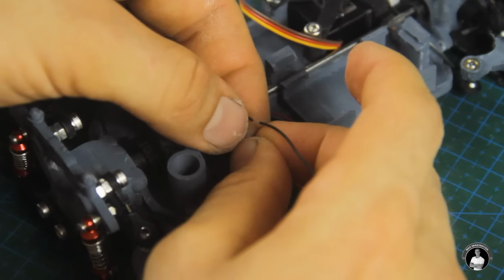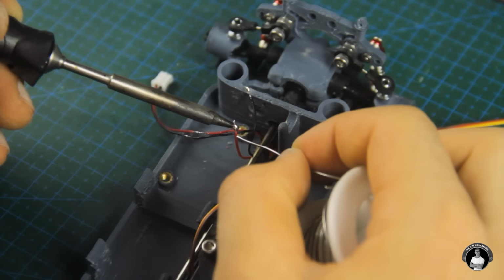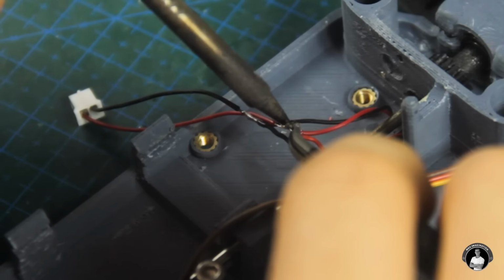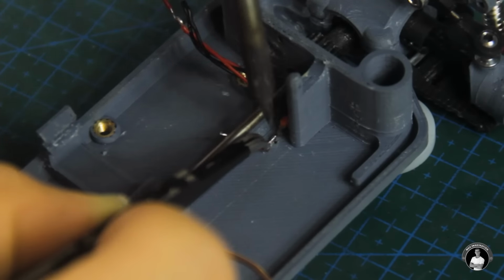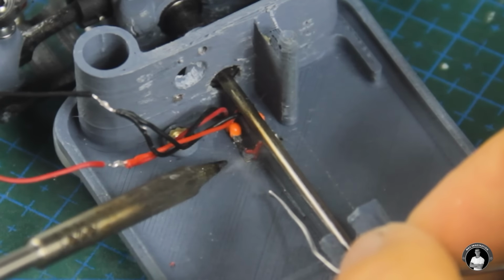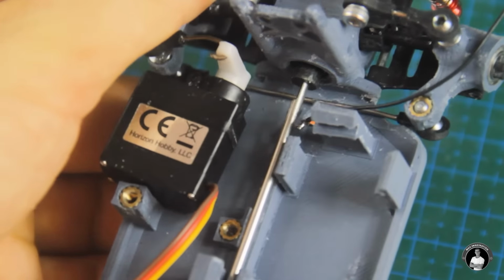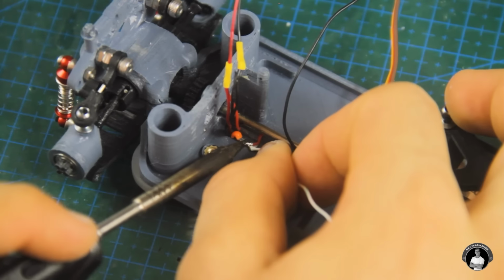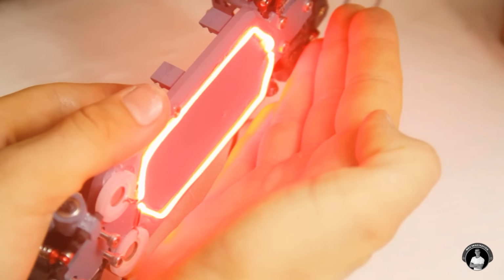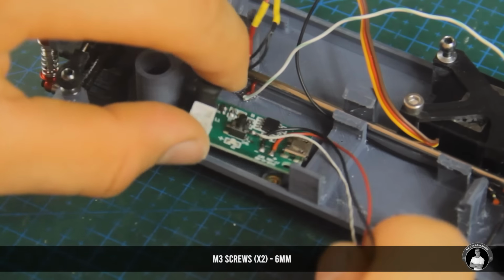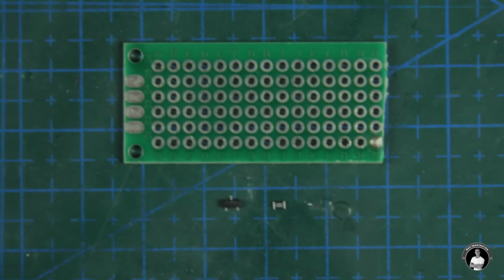So next we're going to wire the 2 water vapor modules together in parallel with one connector. And then do the same thing with the LED filaments, wiring them in parallel with only a wire coming from each end. These LED wires get quite bright at only 3 volts. Next, we can secure the humidifier modules and power supply with the shortest possible screws.